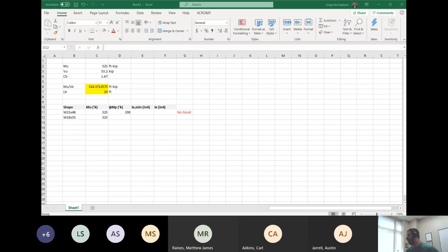Miss Payton, I'm calling on somebody. Oh, okay, never mind. Mr. Schwartz beat you to it. All right, so you got 420. So, Mr. Schwartz, is this section good or no good? No good. Exactly. All right. Now, we're going to go with Miss Payton. All right, so the W21 by 48 doesn't work. The W18 by 55 doesn't work. What's the next section?